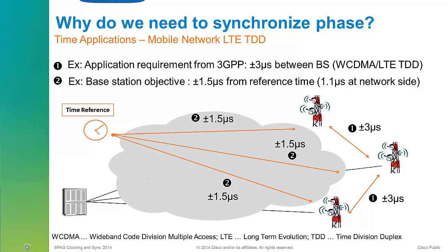So imagine you're on a cell site and you're talking away and you go to hand over to the next cell site, and your time slot comes available on the next cell site, and you find out you're out of phase. Oops, you're starting to transmit when the cell site thinks it should be transmitting, because that cell site is out of phase with the cell site you've just left. So you'd immediately get a dropped call and have to remake the call. Anyone moving between cell sites that are out of phase synchronization in this radio technology would have a dropped call.